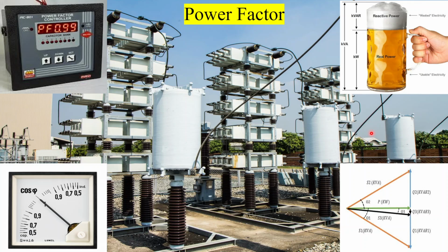Next, improving the power factor is often desirable because it can increase the efficiency of the power system. This can be achieved by adding capacitors, using a synchronous condenser, and installing power factor correction equipment. Adding capacitors can counteract the effects of the inductive load, thus improving the power factor.